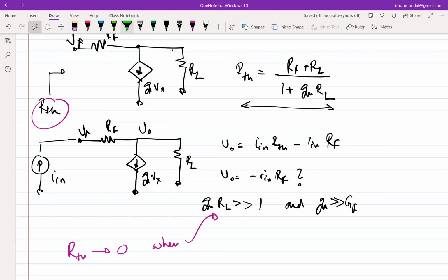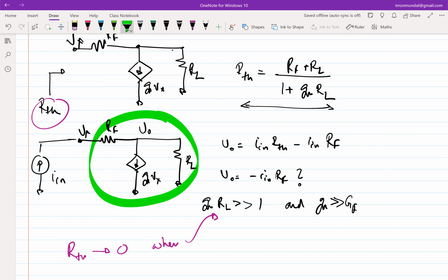This entire contraption is a control source. So does it behave more like a current control source or a voltage control source? Current control source, because input impedance is 0, right? If these conditions are met, input impedance essentially goes to as low a value as you want. One can always argue that if I put in a current source, the current from the source doesn't have anywhere else to go but into the circuit, right? So what's the big deal about the input impedance?